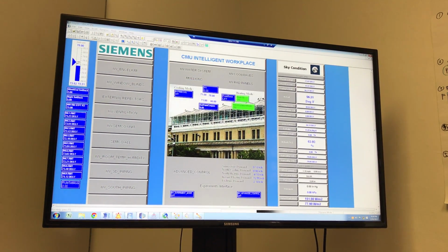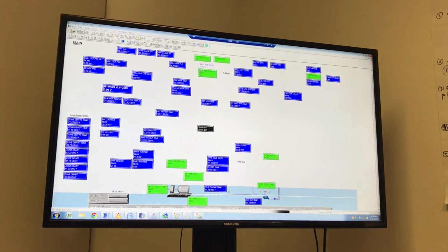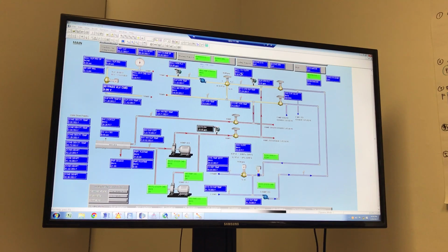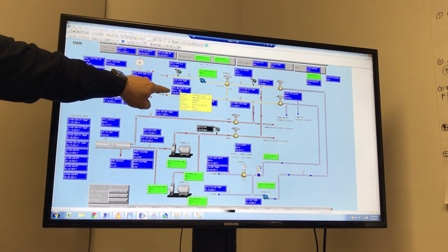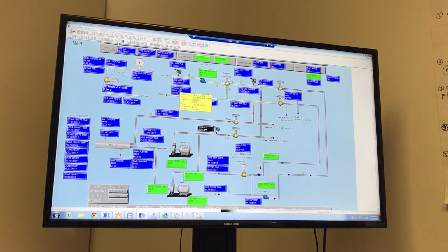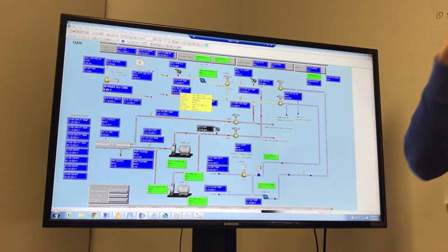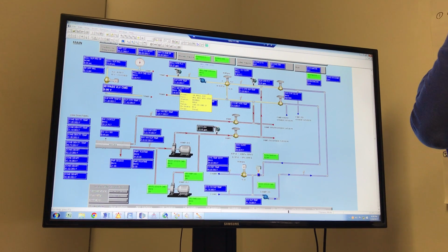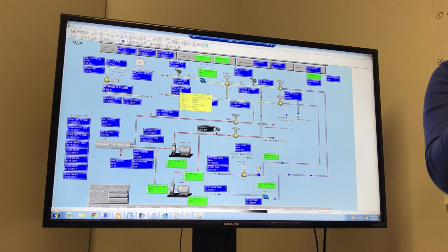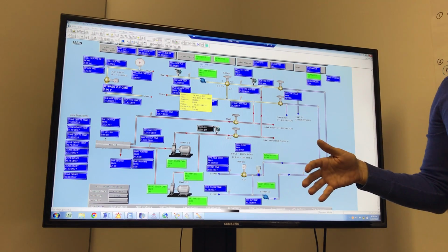Here it shows you the system set point. So now you are below set point. So the GPM will increase. What the system is going to do is realize that now I have 2 degrees offset. The set point jumped to 140 degrees. If it's more than a 2 degree difference from the set point, it just blasts to catch up fast, which means it requires more and more hot water.